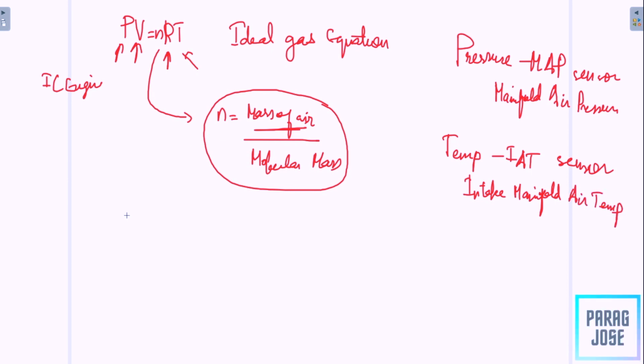That would give us the information on P as well as T. Now R is an ideal gas constant, and V is the volume, or sweep volume, inside the cylinder, which can also be determined. So finally we'll be able to find out n, the number of moles. So n is equal to PV by RT.